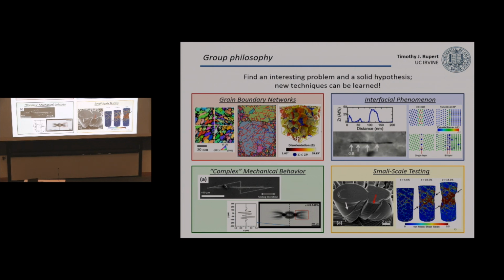So we wanted to think about, rather than just saying I have a certain number of this type of grain boundary, the connectivity or some sort of metric about how these things connect. And we started thinking about what are called twin-related domains. So it's a whole chunk of material where every grain is related by a twinning operation. Okay?